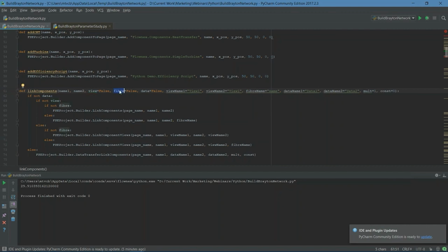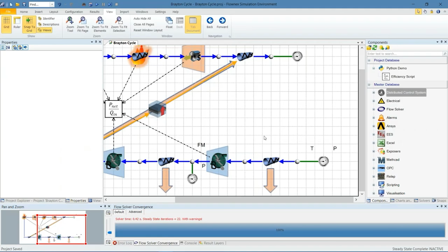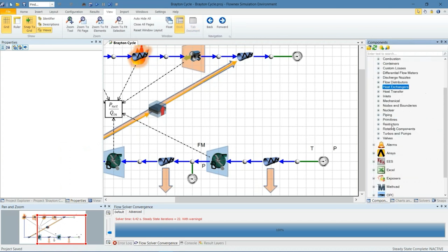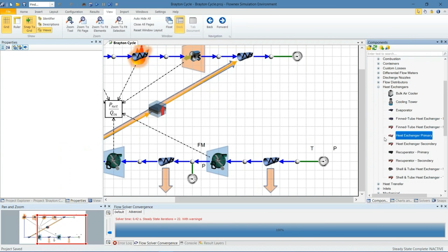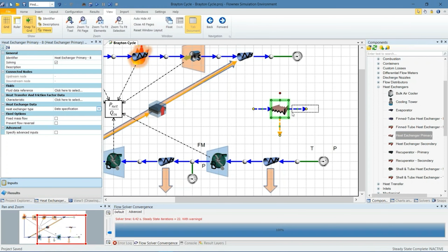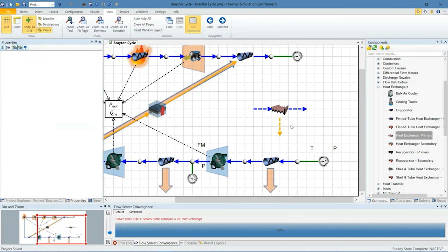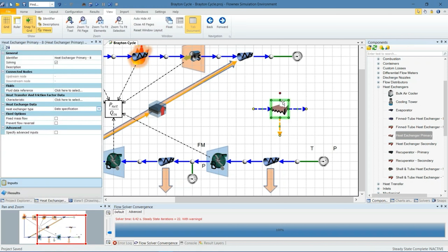There is a case when there is a component with more than two fibers. This logic that I spoke about with specifying the node and then the component works if there are two fibers, but if there are three fibers, for example, then that logic falls apart. That common case would be, say, the heat exchangers. Here we have one upstream fiber, but two downstream fibers. So specifying the order isn't enough to explicitly define which fiber you're using.